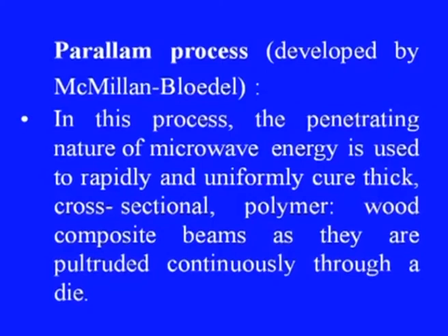Then there is one process that has been developed by Macmillan Bloedel. This process is called the parallel process. In this process, the penetrating nature of microwave energy is used to rapidly and uniformly cure thick cross-sectional polymer, wood, composite beams as they protrude continuously through a die.